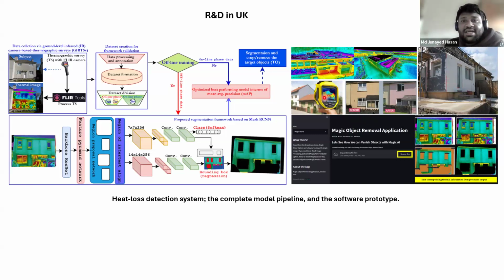So this is kind of a thermography camera. It takes a picture of the building, and from the color values, it understands which part of the building is very hot. You see this red part is very hot, and the green part is okay. There are several color temperature codes over here. From this color analogy you try to understand, and there are also different values in the data, but I'm not going into the data description. So you could understand, okay, there might be a problem.